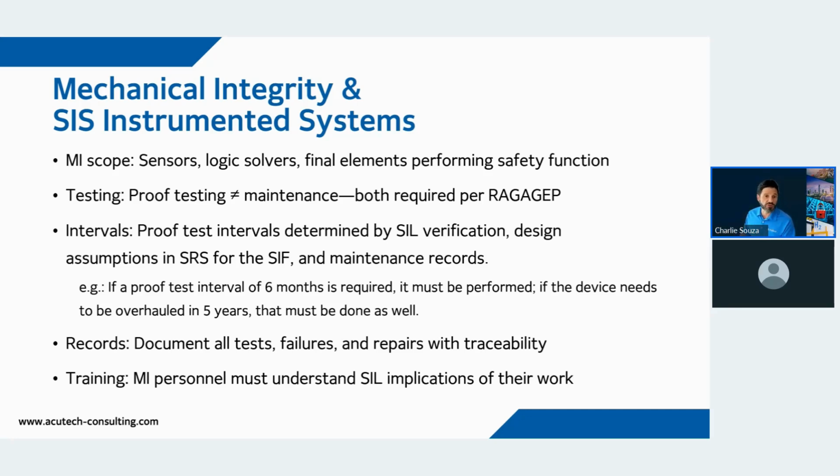And even though you know that a Rosemount may last 5 years, may last until your next turnaround, but to keep that proof testing, to keep the calculation in check, or to keep that risk reduction factor at that same level, the proof testing needs to be respected.